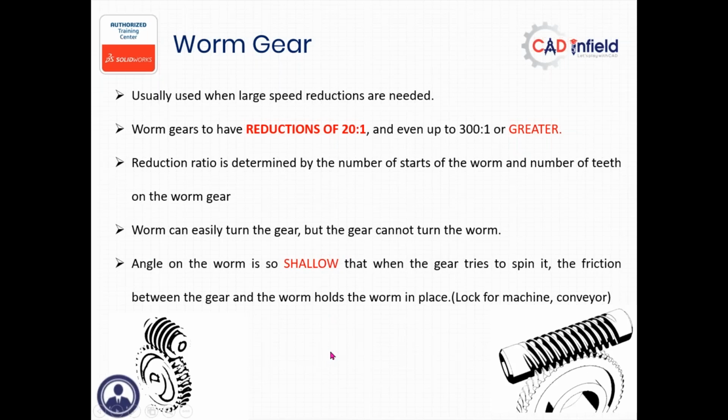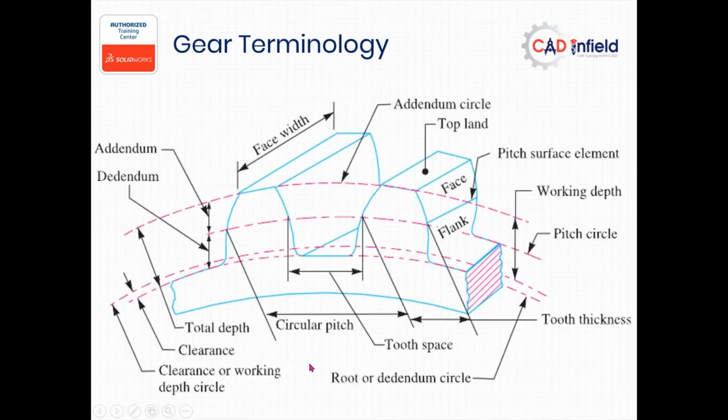But we don't want to go into detail on it; there is enough material already available in books. For us, we know that we have one PCD, on which all gear selection is based. One thing is clear to you: the PCD, the pitch circle diameter, is basically an imaginary diameter which is used for the specification of any gear. The upper diameter is called the addendum diameter, the lower is called the dedendum, and there is a root diameter below that.